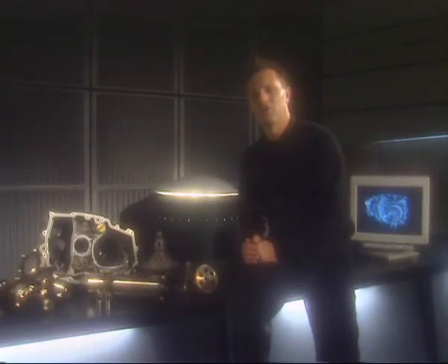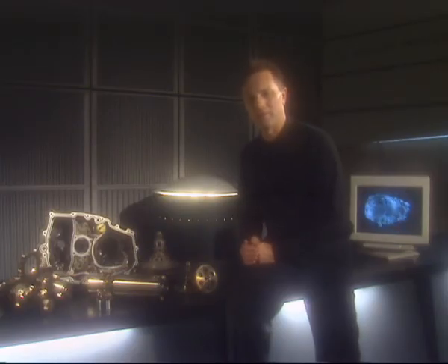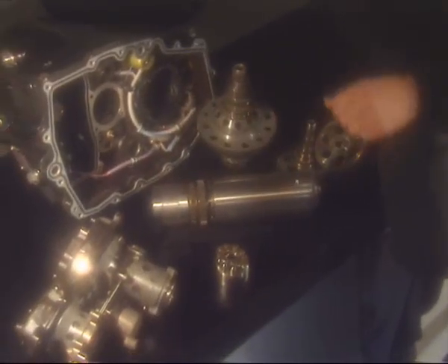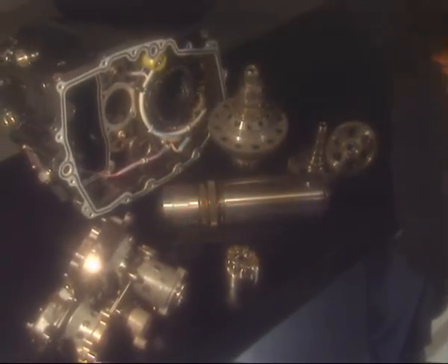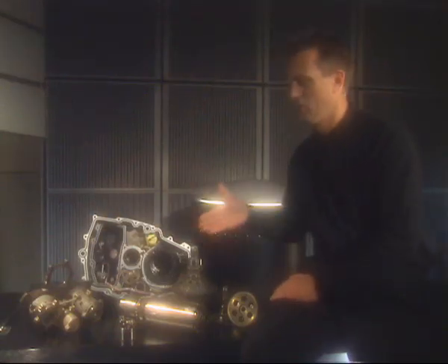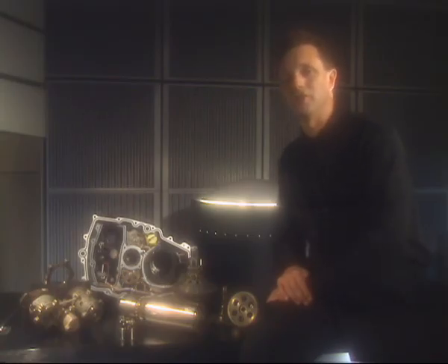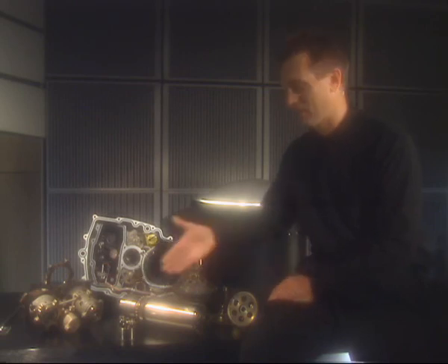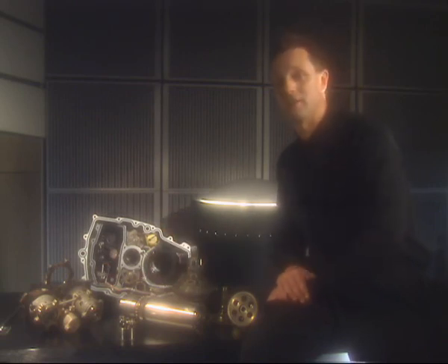The integrated drive generator, IDG, provides electrical power for all the aircraft systems, and therefore its reliability is of the utmost importance. It consists of a generator and a constant speed drive, CSD. The CSD converts the variable input speed of the engine into a fixed rotation speed for the generator. Thus, the generator is able to provide a fixed frequency for the aircraft electrical network.